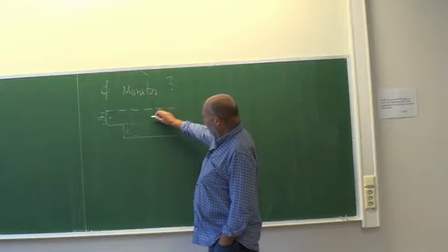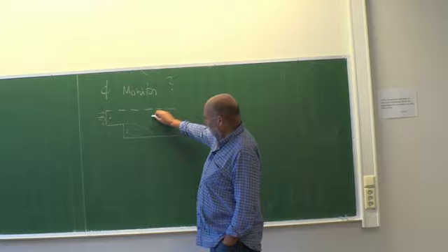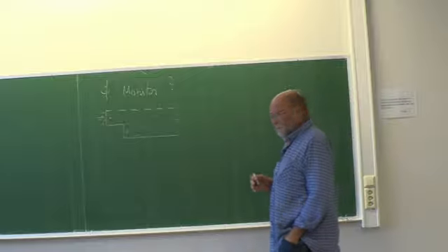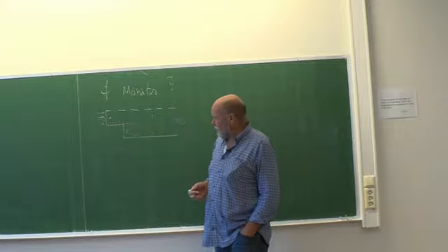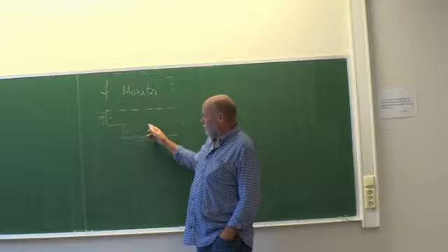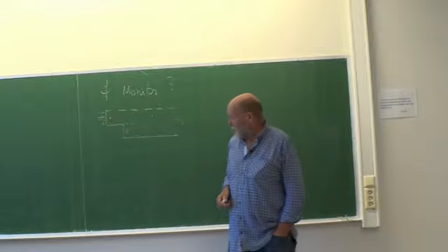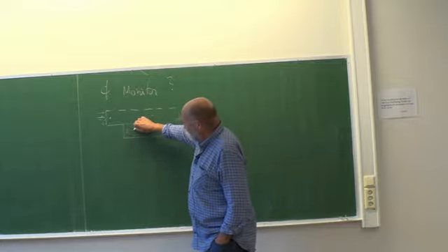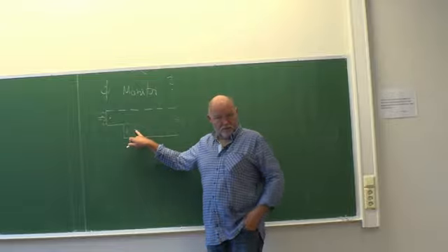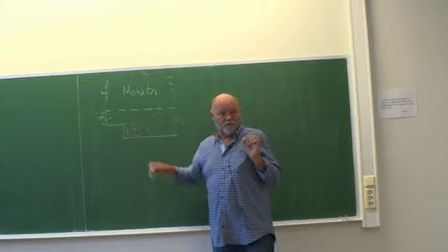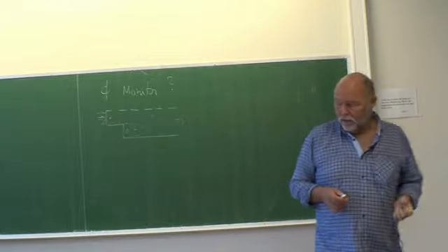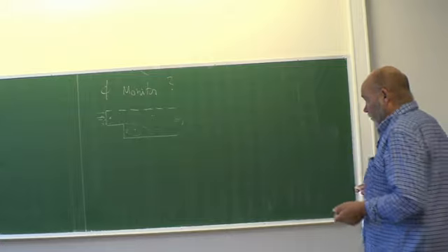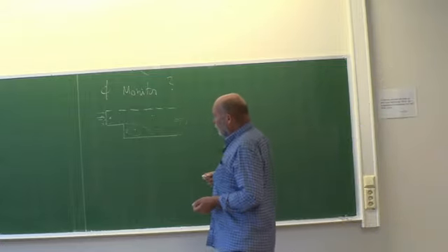If you take a velocity at a given point over here, it's not so sensitive for this problem, is it? The essence, the important part in this problem, is actually the reattachment zone behind the step. So if you had taken a velocity at a given point, maybe somewhere here, that might be okay to use as a monitor point for the velocity.